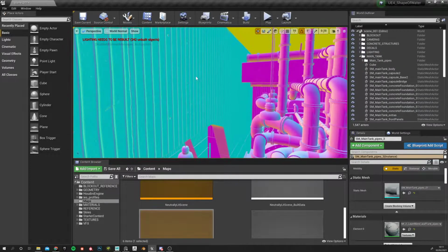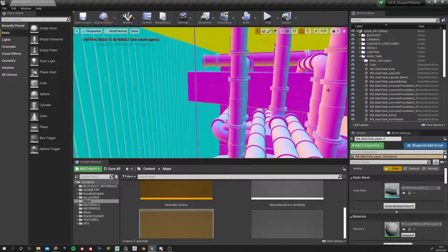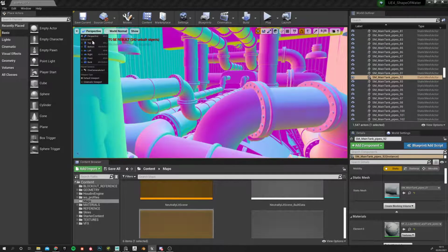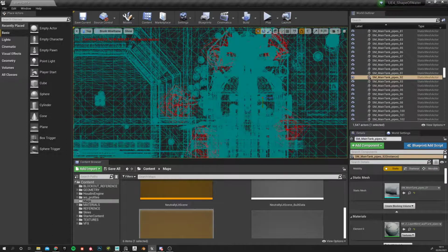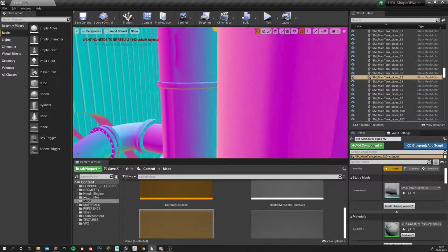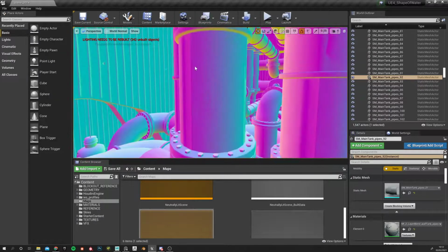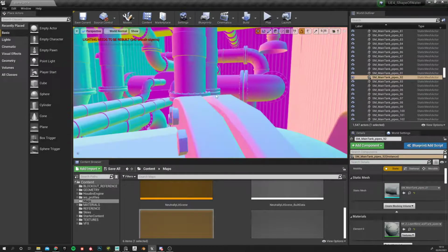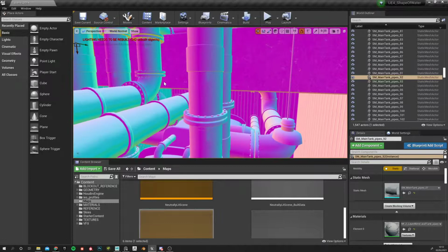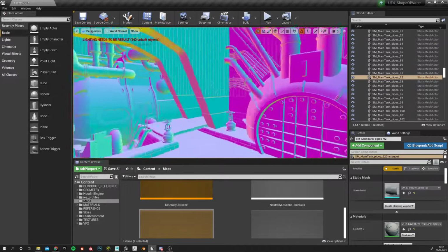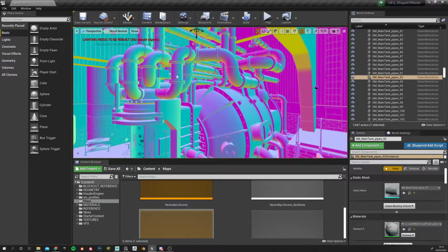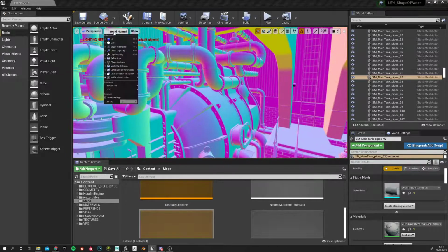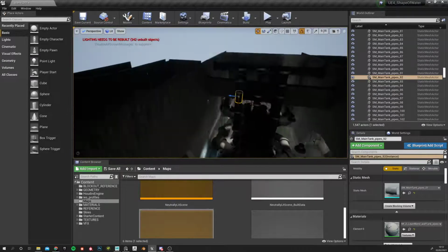You can see I just placed them around and blocked them in. I didn't go exactly, like this one is exactly 100 units. I just eyeballed them, going from the top view and then trying to match them on this side and things like that. At the moment this pipe has the same shader as this one. You see that this one doesn't have any artifacts, but this one does. That's because the UVs are slightly different. I just used it so I can have something in there, which I shouldn't have really, because I could have left it just with the lambert, so it would be easy to place. When I did the placement, I used this buffer visualization because it's easier for me to see, instead of the normal lit mode, which I cannot see very well.